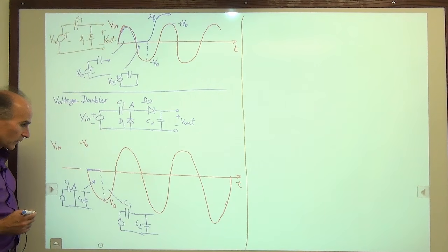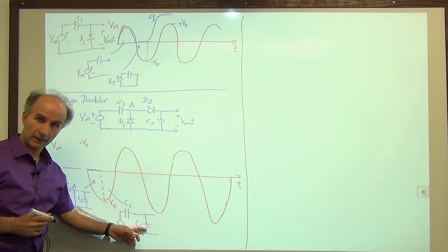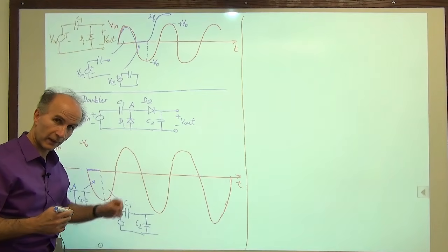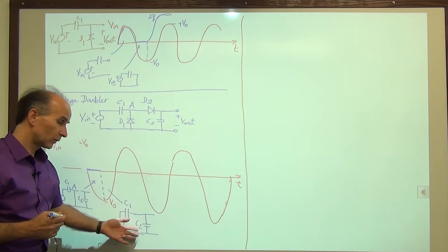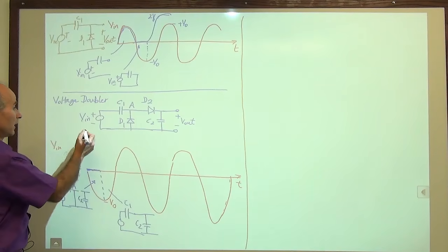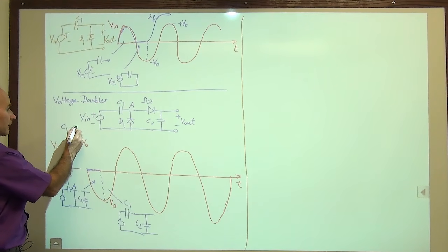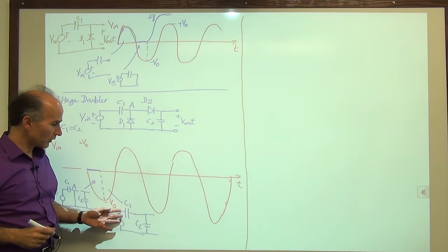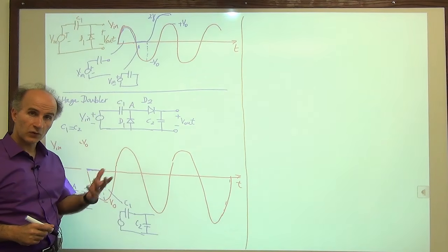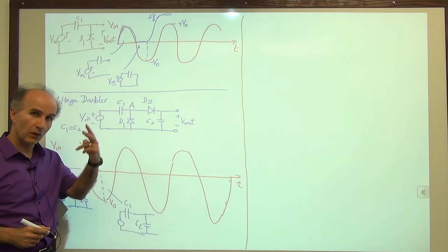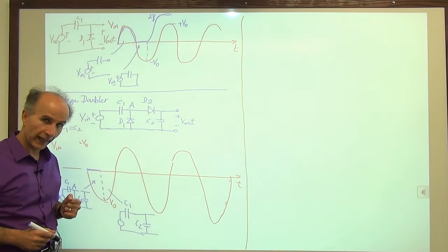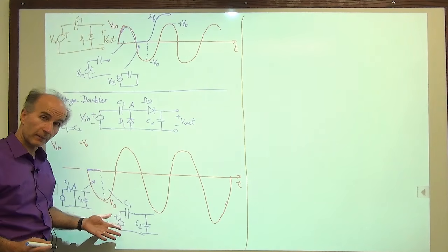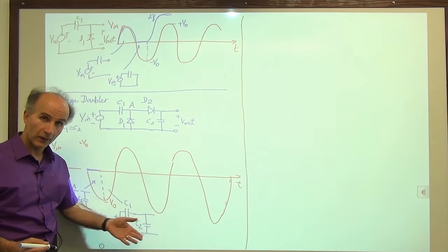Okay, so do we know the circuit? Yes, it's a capacitive divider, as we remember from the previous slide. And let's say C1 and C2 are equal. For simplicity, that's usually the case anyway in the design. So that means that the attenuation factor from here to here is just 1/2. Because we have C1 over C1 plus C2, it's 1/2. That means that if this voltage changes by some amount, this voltage changes by half of that amount.